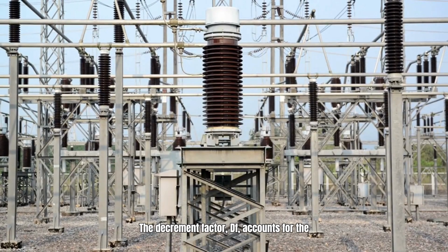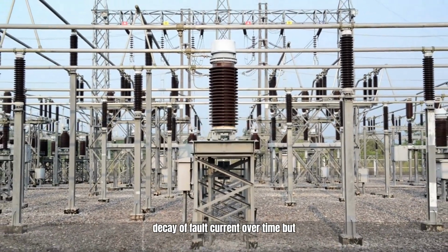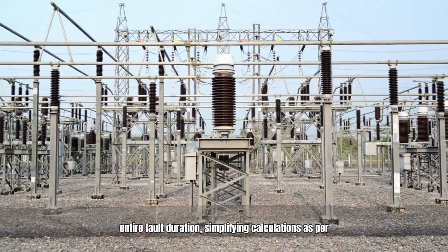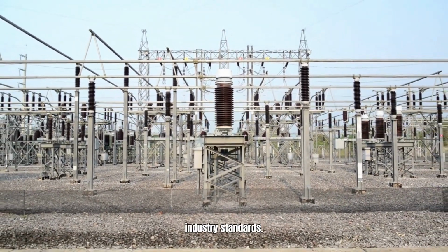The decrement factor, DF, accounts for the decay of fault current over time, but is typically taken as 1 for the entire fault duration, simplifying calculations as per industry standards.